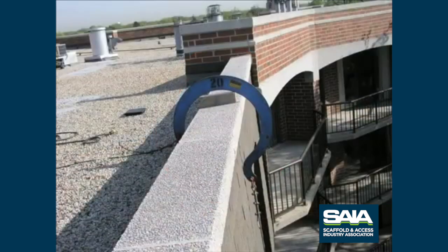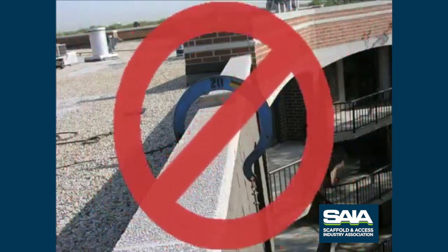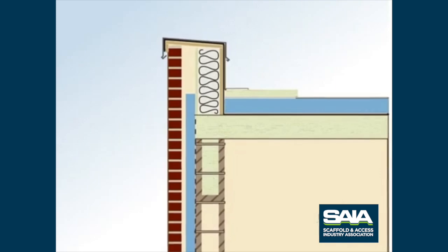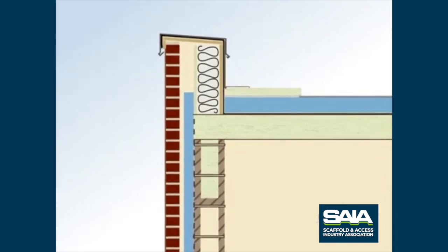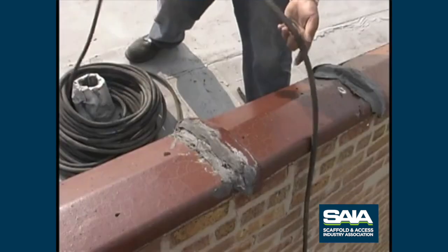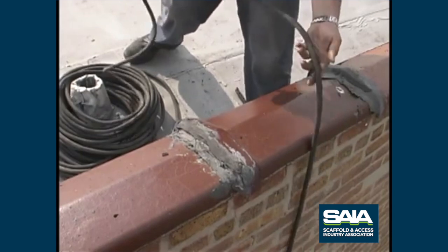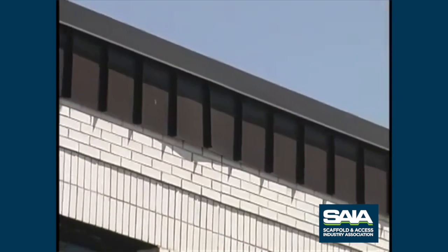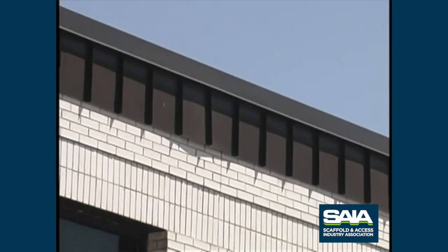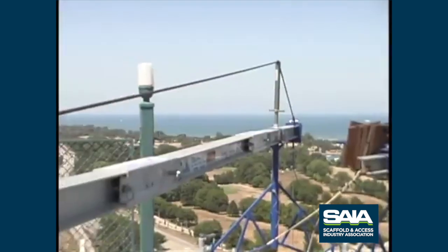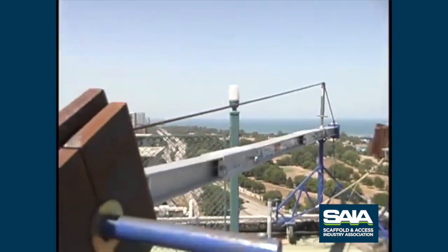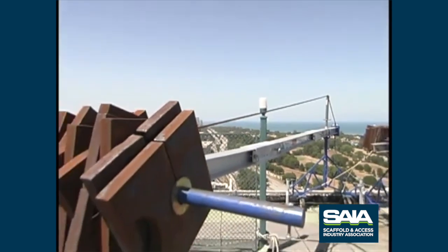If any questions exist, do not rig from it or rest a beam on it. Qualified persons who provide structural drawings of a parapet must beware of block, brick, stone, expanded foam, or metal-covered parapets, which probably will not take the load. Counterweighted outrigger beam systems should be used when the parapet strength is questionable.